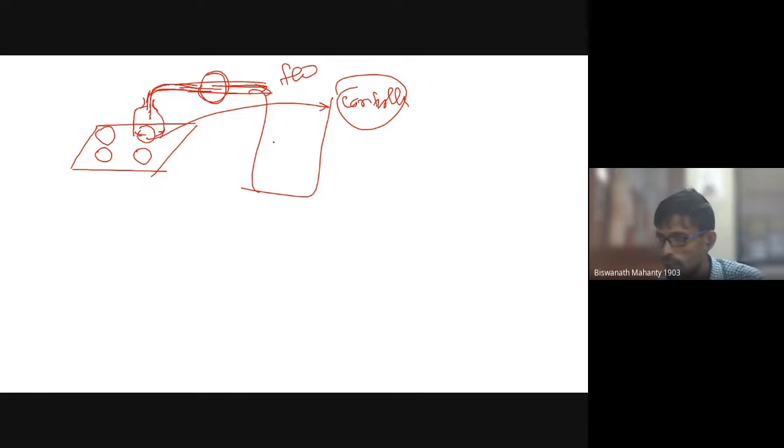This information is transmitted by a transducer to the controller, which decides that this much weight was there and after this time this is the change in weight. If we give the specific weight information of the media, we can calculate the possible flow rate of the liquid. So liquid flow rate measurement is really not so difficult.